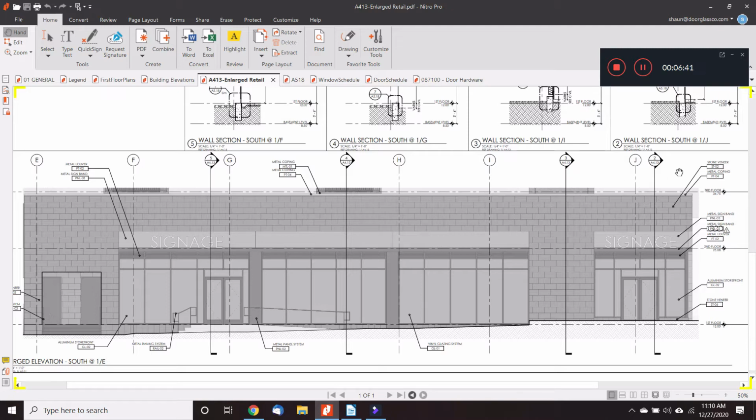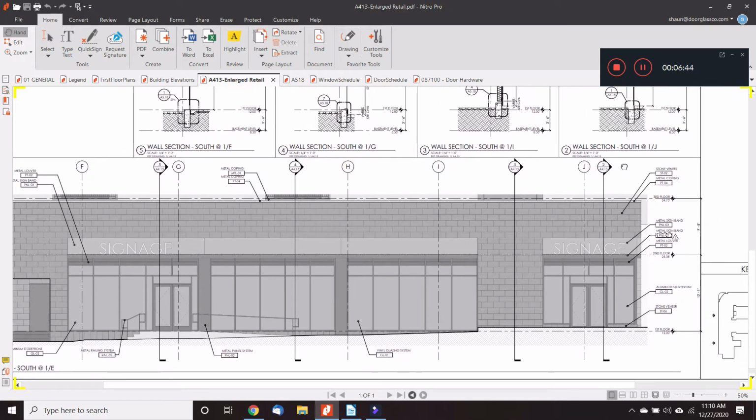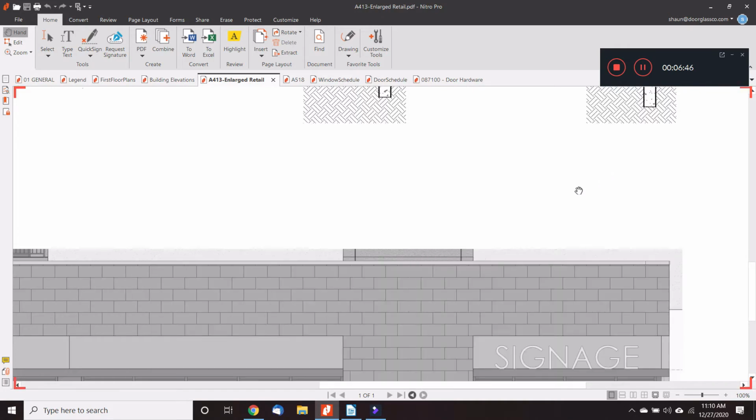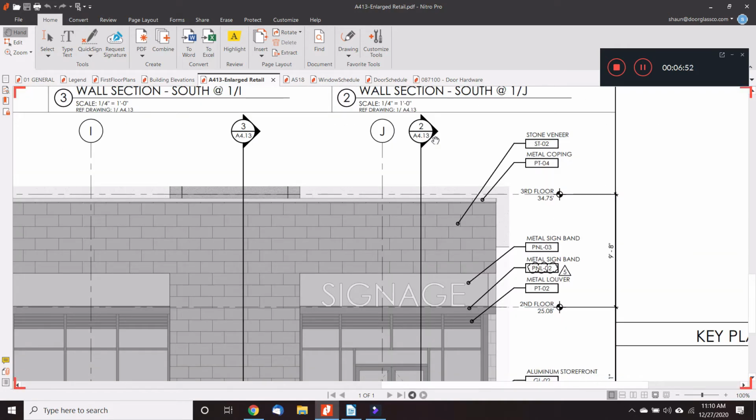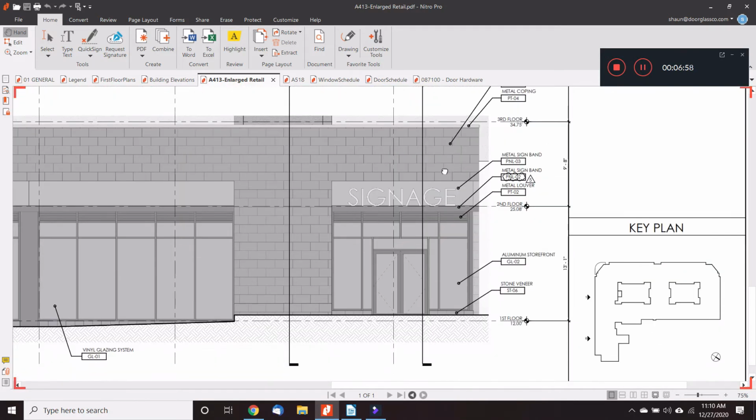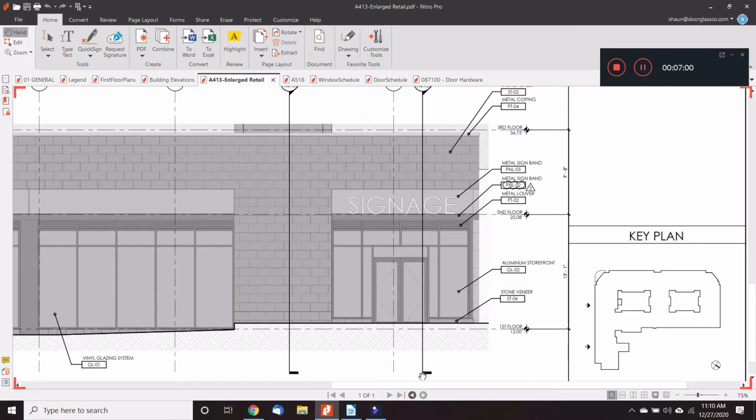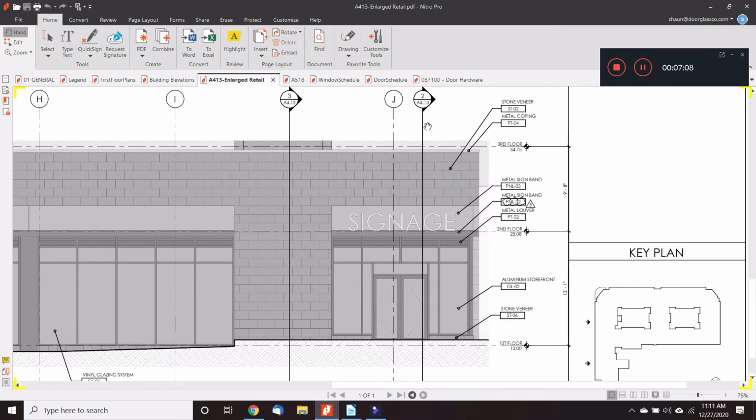Okay, on this drawing we have some section markers. In particular, we have 2A413, and that's a line. You can see this line is going through the drawing, okay, and it has a little symbol at the end to indicate that it's closing this section of points. The line faces to the right, so if we find drawing number 2 on A413, we're going to see a drawing as if the wall was cut through and we're looking this direction.